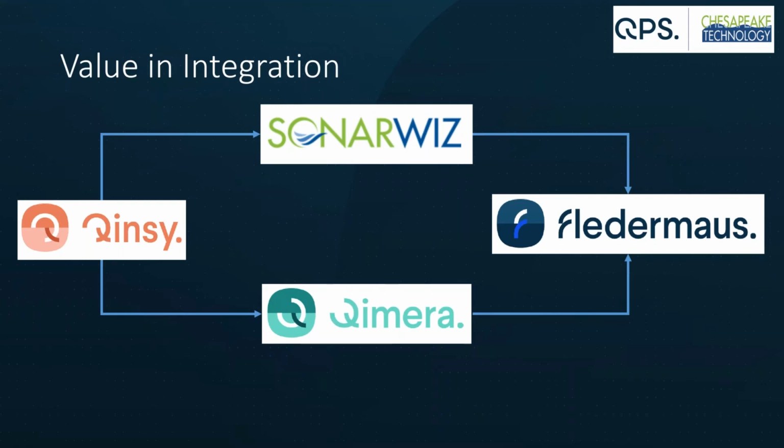And I see another question here. What is the best method to obtain a survey area geotiff? You can do it from a number of different places. You can either take a screenshot from Google Earth and then geo-rectify it yourself. I like to use Global Mapper to do that, which is quite nice. They link directly to the online databases. There are also various online databases that you can use to download the geotiffs of a certain area as well. Okay, good question.